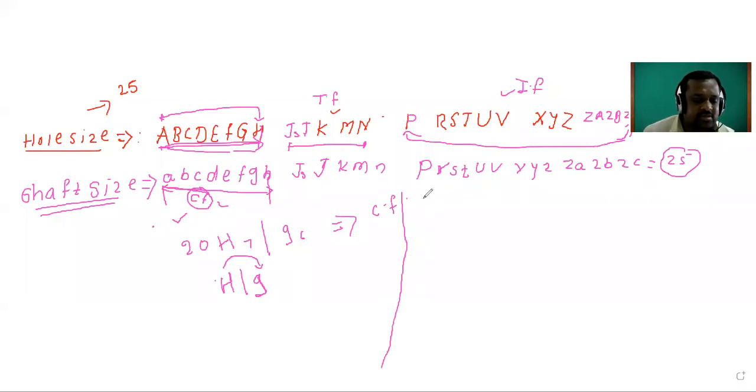Yes, sir. So take the next example. If such a condition is there, H7/P6, then tell me. Again see here, it is the capital H. Capital H lies between A to H, so to identify the fit, where do we have to go? We have to go this side. Look where small p is. Small p, again a similar process.